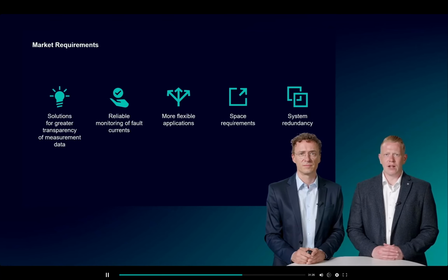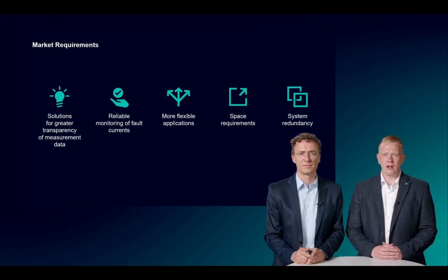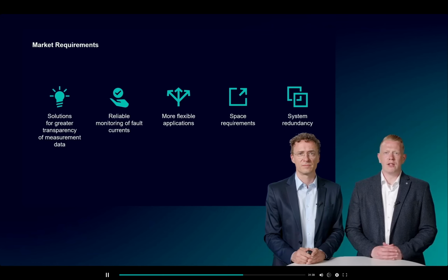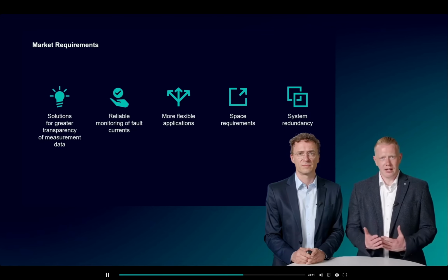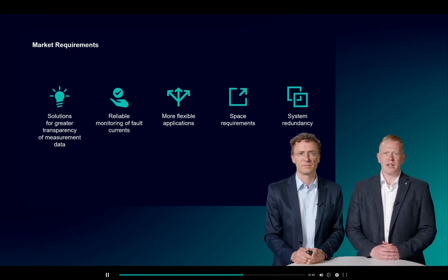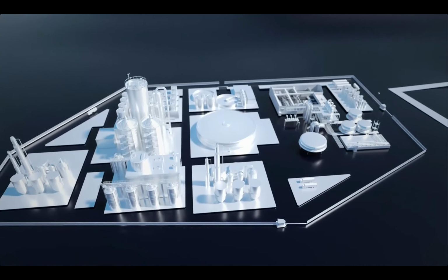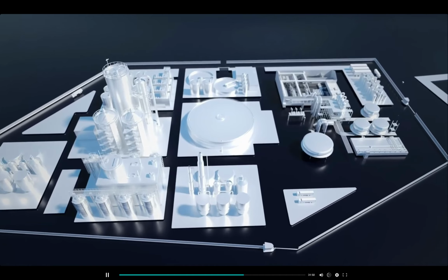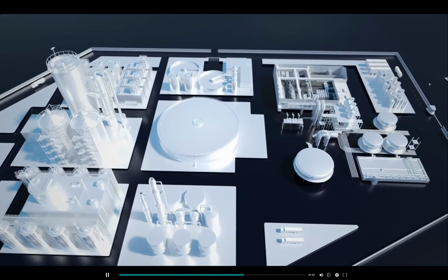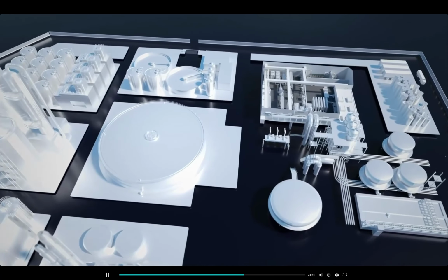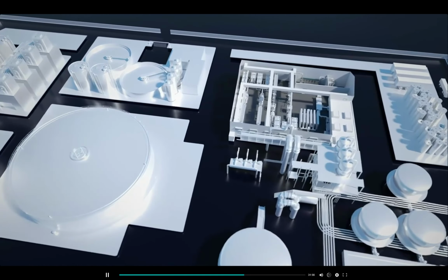The initialization module is integrated into your switchgear. This ensures that feeder-specific parameters, addresses and data are assigned to that feeder's compartment. When replacing a withdrawable unit, the new unit automatically configures itself from the initialization module. At the moment you reconnect power, all settings and other parameters are restored, with minimal interruption, the motor starts up and is running again at the same time, and communication is re-established.